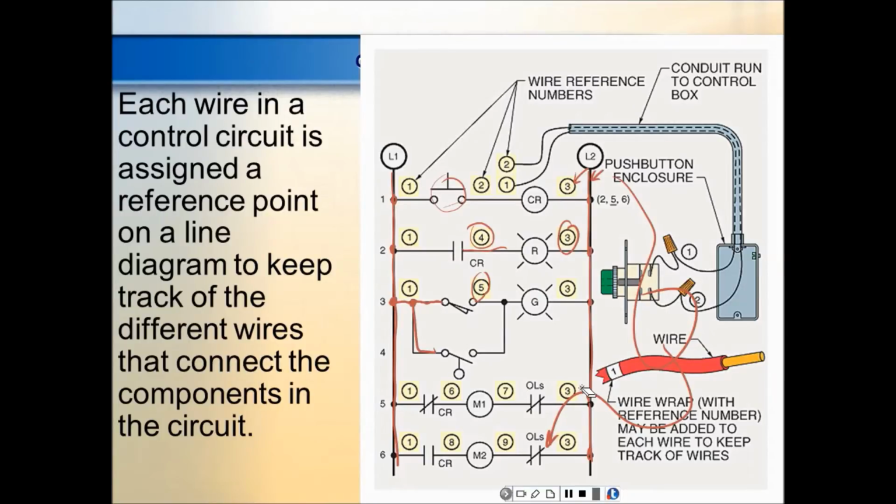You understand? They don't have to buy, okay, we run 3-phase, it's supposed to be red, blue, green. They don't do that garbage. They run all the same color wire. The only time you'll see different color wire at a plant like that is if they pull a cable. And so a lot of your signals come through cables, but when you get into these control circuits, they're usually all one color. And industry likes to use what? Black.